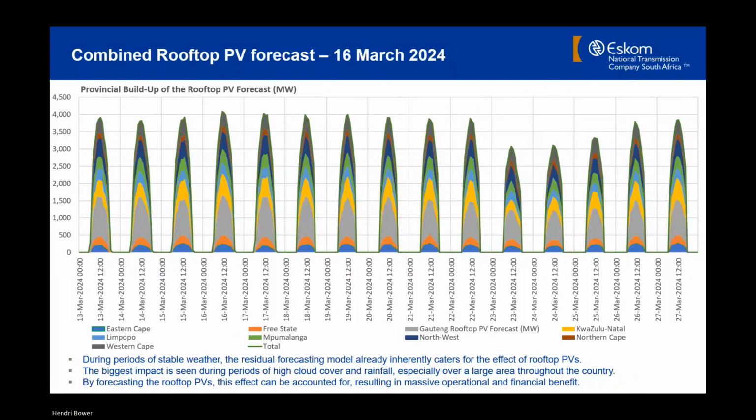He says, even on cloudy days, PV still gives an output. Do you assume that the PV generation goes to zero or some other percentage? If the latter, what percentage? And I guess this is about the clouds not stopping it. Yeah, no, I agree with that comment. No, I don't assume that it goes to zero. And that is the reason why, especially for the forecast, I use solar radiation as an indicator for the forecast and not cloud cover. And rightly, as mentioned, even on a cloudy day, there's lots of radiation that's still available so that you can extract energy. So I use that as an indicator and not necessarily the cloud cover.